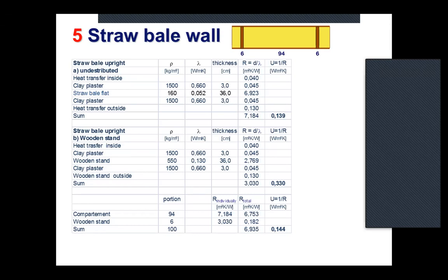It's always better. Yeah. If you calculate that by hand, you have to do it similar to how Ubakus does it. It makes 3 layers: one layer 14 centimeters, the layer in between 8 centimeters, and then a third layer 14 centimeters again. And then you add these numbers which you get. So the 14 centimeters includes the wood, the 8 centimeters is just straw, and the 14 centimeters again is similar to the first 14 centimeters, including the wood.